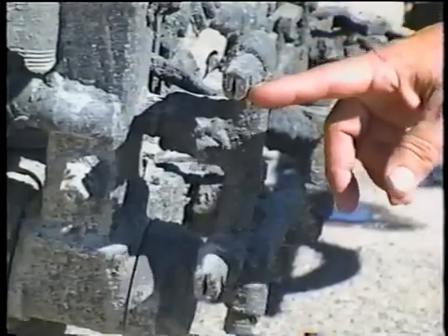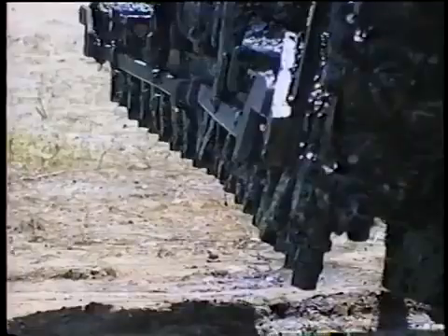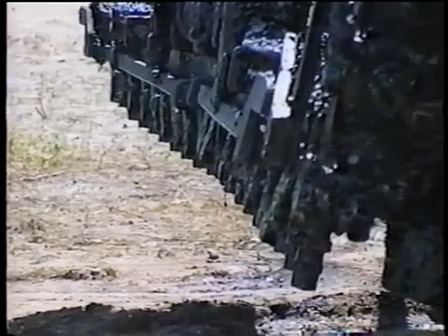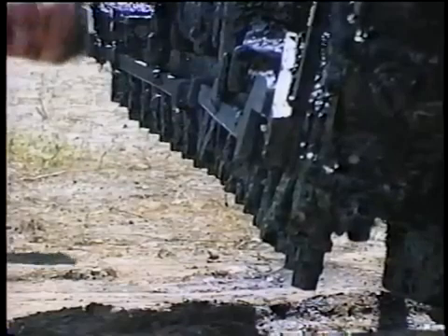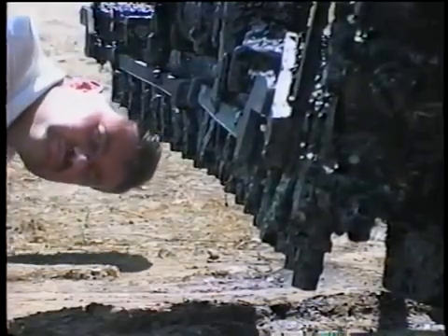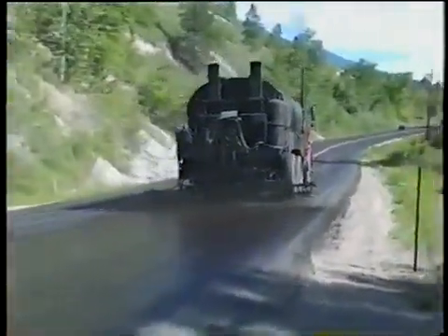Next, look at the spray bar, starting with the nozzles. They all have to be clean and angled in the same direction to get the proper coverage. And check the height of the spray bar. The proper bar height, nozzle angles, and application pressure determine the quality of the tack spray pattern. Generally, you want a double or triple lap coverage.